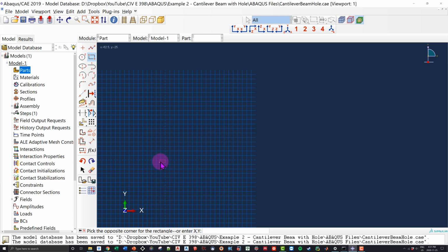So of course I have that point, and then I want to specify the point of the beam all the way on the top right corner, which we know occurs at 2000, because again, I'm doing things in millimeters, and it has a height of 250 millimeters, so I'm going to go 2000, 250. We can see it down here, and when I click enter, it creates my beam.